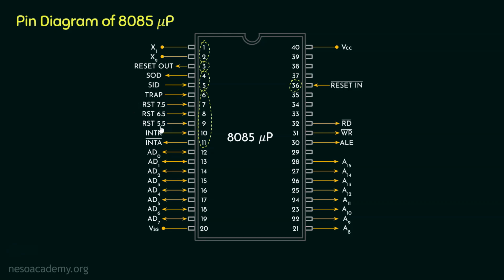These are used by the software instructions. Thereafter, we have got the interrupt request pin, which is used by low priority interrupt devices, that is keyboard and mouse. And for both the restart and the INTR interrupts, the 8085 microprocessor will have to generate the interrupt acknowledgement active low signal so that these interrupts can be serviced.